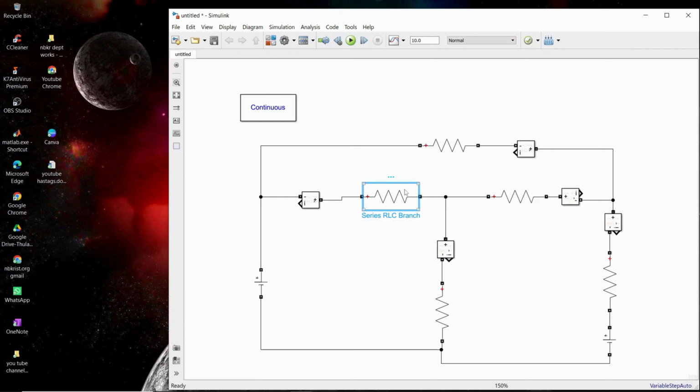Now if you want, you can define the values. All are now very clear. So this is of 30 volts, and this is also of 30 volts. I'm taking this as a reference. Therefore current is leaving in this direction, current is leaving in this direction, current is leaving in this direction. For this node, current is entering, current is leaving, current is leaving. We just need to verify.